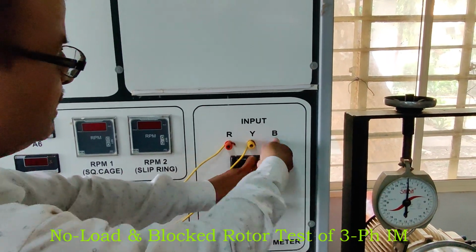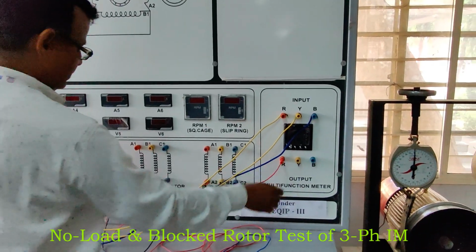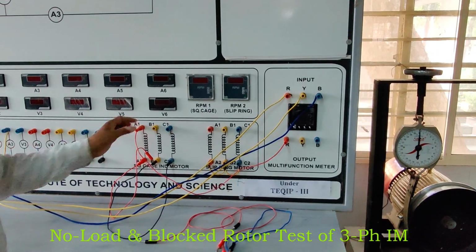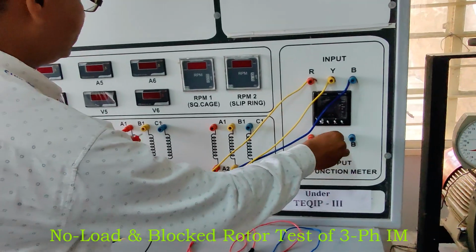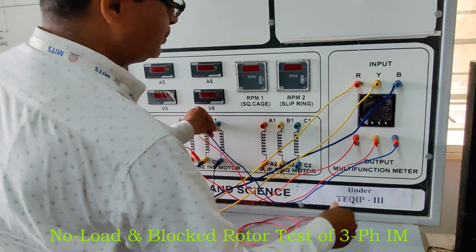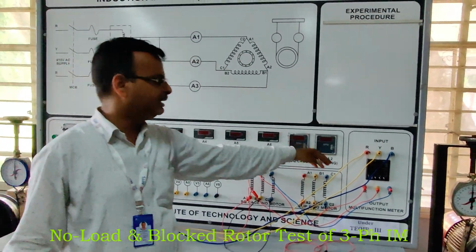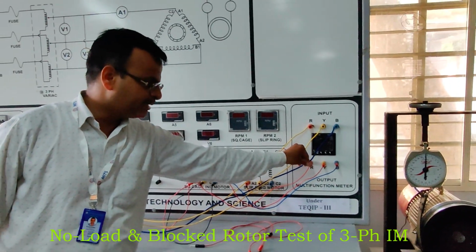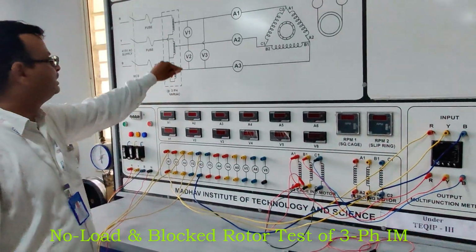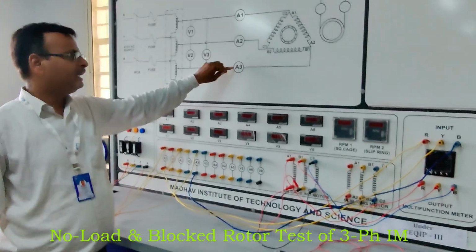The output terminals of this multifunction meter connect to the stator terminals: R to A1, Y to B1, and B to C1. So the multifunction meter is attached at those positions. It will measure the no load input power and the no load power factor. And these are A1, A2, A3, connected in the lines, so they will measure line current.